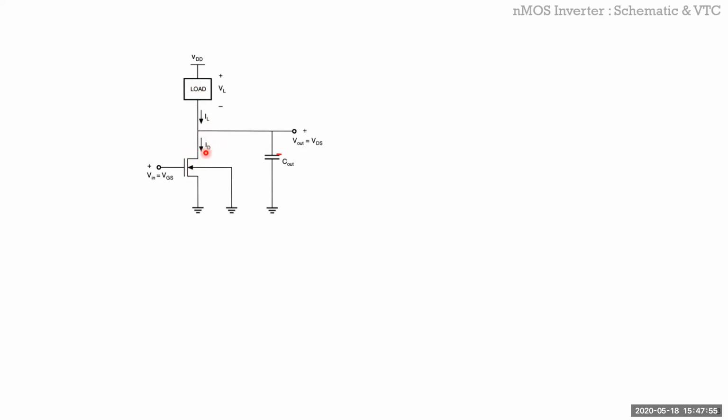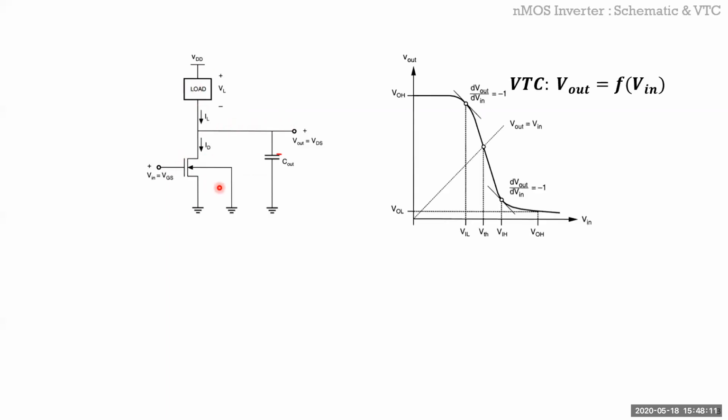And that's where CMOS came into the picture, where you actually add a complementary switch. That's why it's called complementary MOS. You added a complementary MOS so that when you're pulling down, you switch this off. When you're pulling up, you switch this on to charge it, but you shut this off, like in this case.